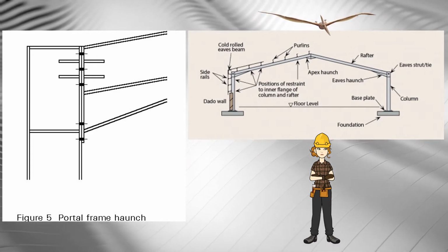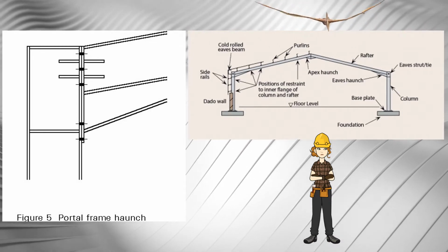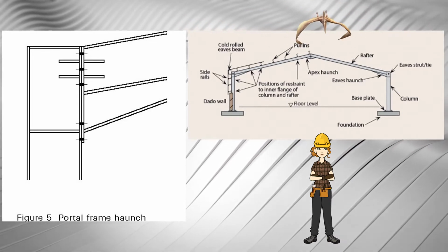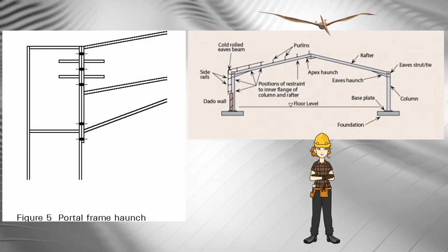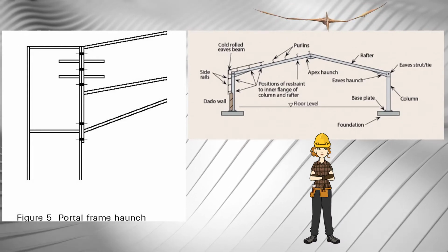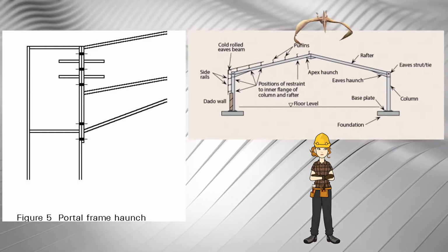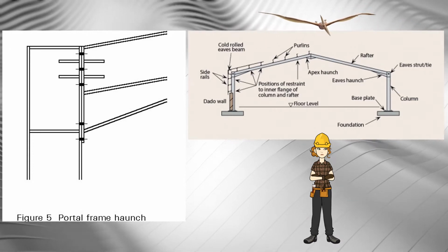When hot rolled sections are used, haunches, as shown in Figure 5, are usually provided at the eave and the ridge. These haunches deepen the overall section, thereby reducing bolt forces. By extending the haunch regions along the rafter, the frame is also strengthened and stiffened.